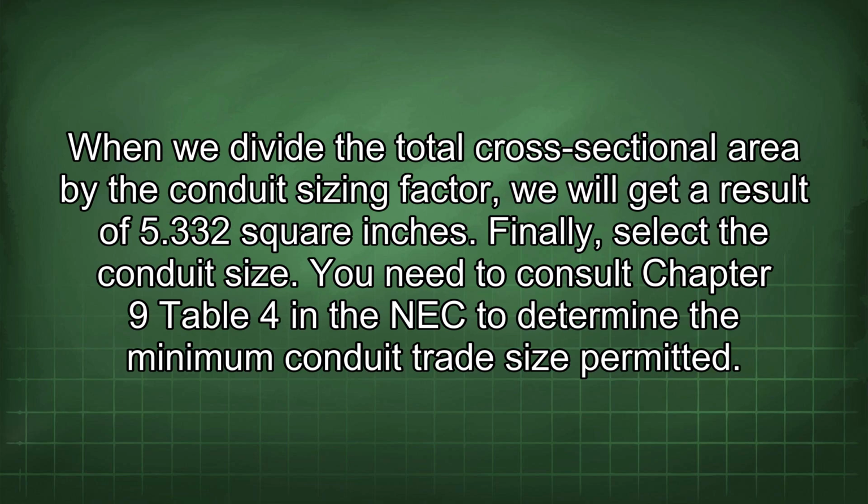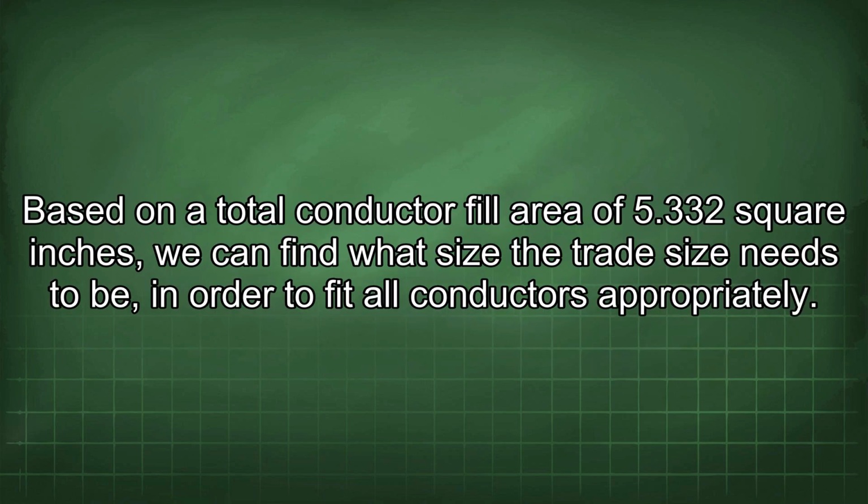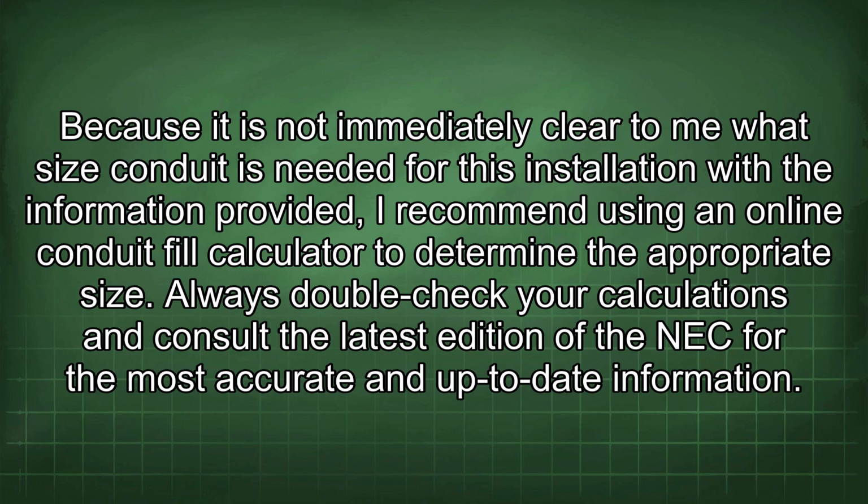You need to consult Chapter 9 Table 4 in the NEC to determine the minimum conduit trade size permitted. Based on a total conductor fill area of 5.332 square inches, we can find what size the trade size needs to be in order to fit all conductors appropriately. Because it is not immediately clear to me what size conduit is needed for this installation with the information provided, I recommend using an online conduit fill calculator to determine the appropriate size.